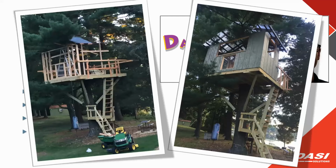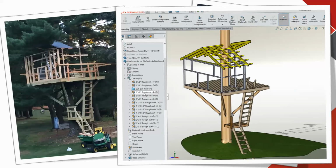And I use SolidWorks for a lot of things. So this design here is a treehouse, and I used SolidWorks weldment technology. And what this allows me to do is use the same type of framework that we would use to create a structural steel shape, but using just a little bit of a different technique, we can leverage things like wood profiles, and that'll give us the same type of cut list. And I use it for form, fit, and function. Whenever I can visualize something, I just simply build it up in SolidWorks quickly and go from there.